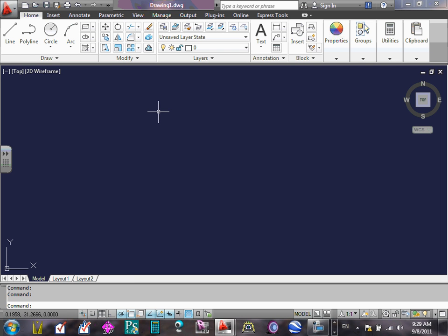If you guys look at them, I have the symbols. I'm going to save this one as E5. I'm going to tell you why E5. Everybody can see sheet 5 here? Everybody can see that sheet 5 is upper level power? Why can't I save it as E1, E2, E3? I'm going to save it as E5 because E5 has two extras, the title block and the background. E1 is just a title block and doesn't have a background. That's why I chose E5, so I can get the most out of this drawing, and then I start deleting things to get E1 and E2 and E3 and so forth.